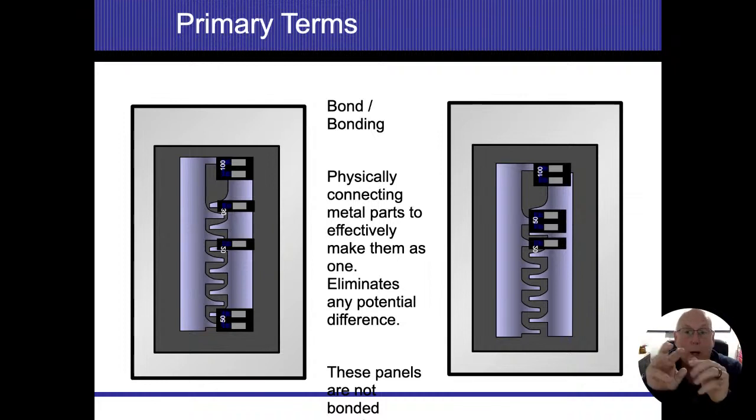If that dryer has a ground plug, a 3-prong plug, that ground prong is going to be energized. So we energize the case, the ground prong is connected to the case, so that's energized. That's going to be energized to the junction box, to all of my conduits, all my plumbing pipes. All those items are connected together. So as soon as I have an energized conductor energize the case, it actually energizes my whole plumbing system, all my conduits, all the cases, and everything else that has a ground plug that's plugged into any grounded outlet.